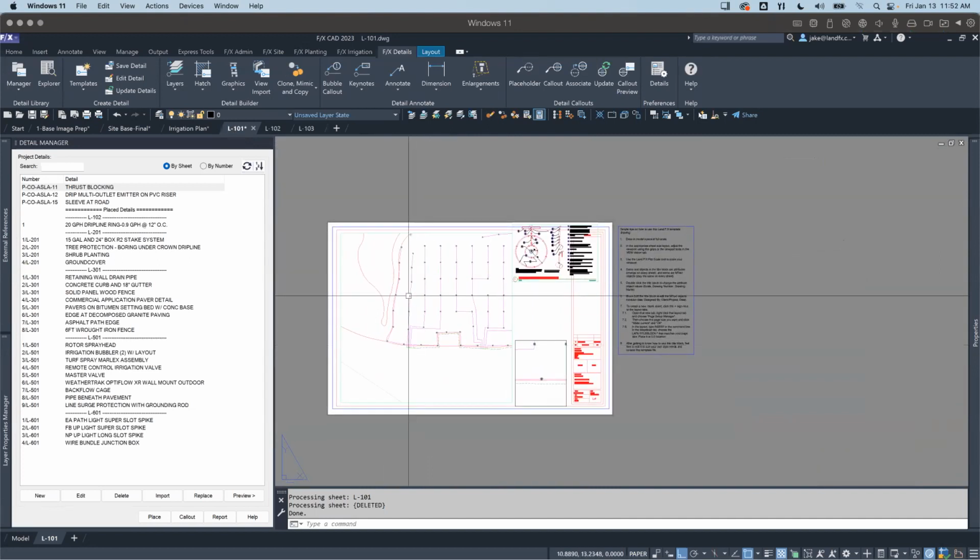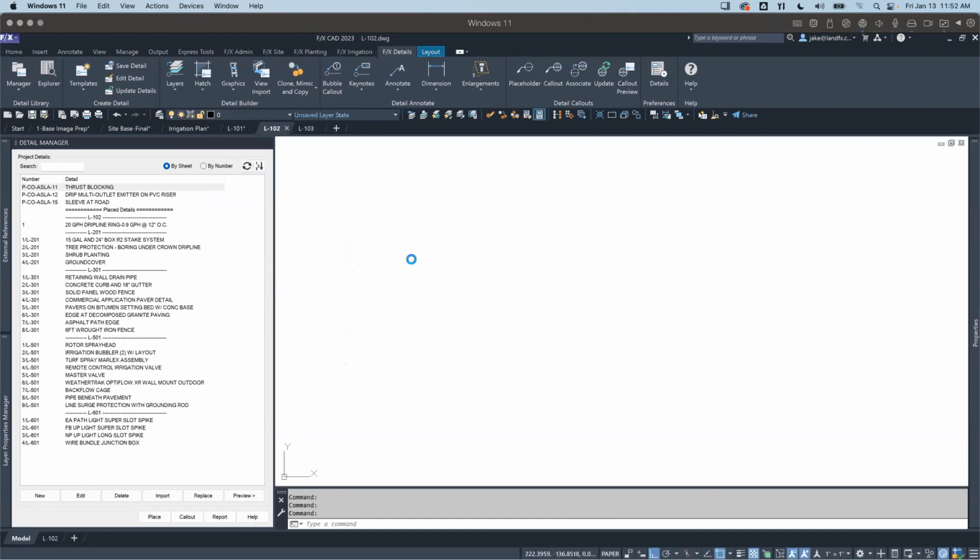And again, placing that preview layout block into that irrigation file is going to allow you to reference that actual point for your next sheets. So you can have multiple files holding that one sheet while still referencing the same location. You don't have to sit there and try to line things up. You already have that reference point of where it goes as you XREF that guy in.